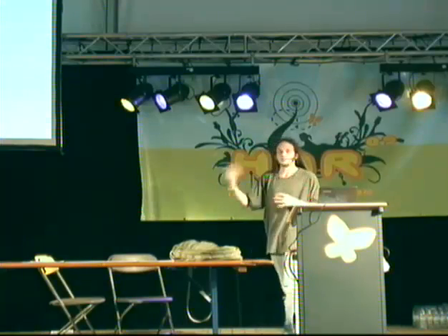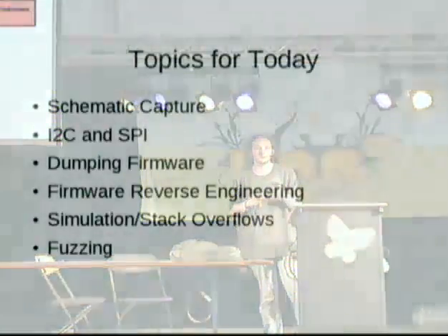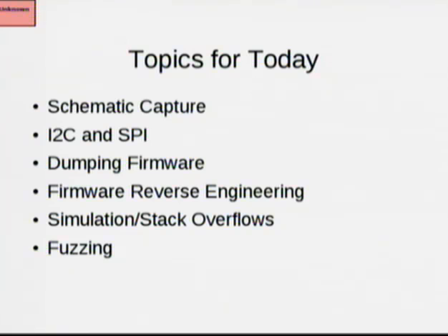So I'll discuss the schematic capture. Given a captured device, you want to be able to figure out which wires contain which signals. And you want to be able to do this as quickly as possible. And thanks to the hardware-accelerated I/O ports of the chips used, you can be guaranteed that the particular functions will run over particular pins of each chip. We'll also discuss the protocols that are used to send data from one chip on a board to another, and how you can wiretap that line of communication, that internal serial bus, in the same way that you might wiretap a network using a packet capture device.